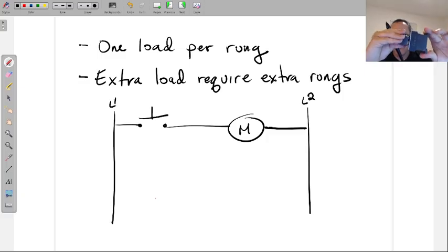So when I place my auxiliary contacts on the motor starter, as soon as the motor starts, these contacts react as well. I have two normally closed contacts on this. Technically, they're in the middle. And two normally open ones on the outside for a total of 4 contacts.